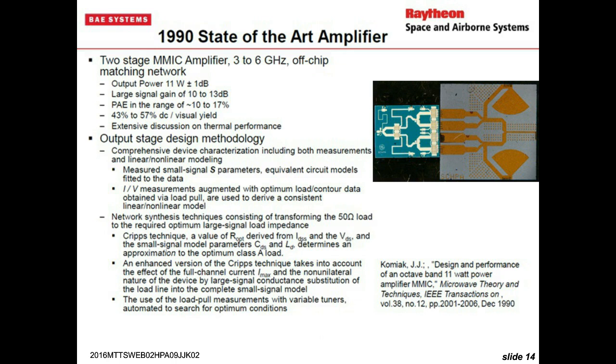We have characterized GaN, and our GaN HEMT PAs at Ka band showed phase noise performance, residual phase noise, that's additive phase noise due to the amplifier, that was as good as or better than the reference amplifier in the system that had been used for 20 years, an old MESFET design. So the power amps do have good phase noise performance, but I would really go to a low noise transistor like a bipolar for the oscillator itself.